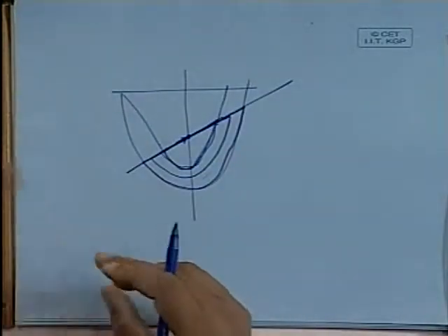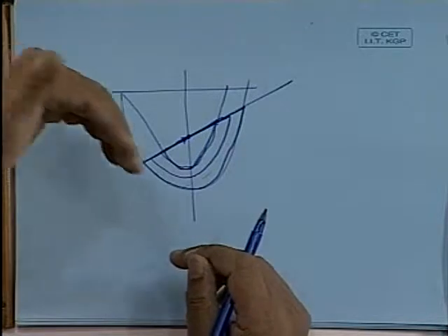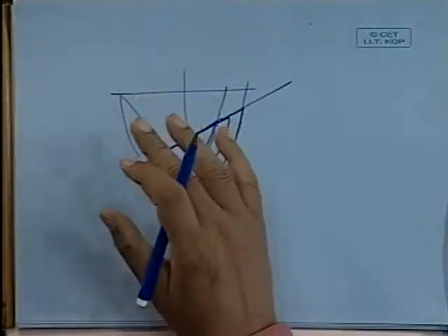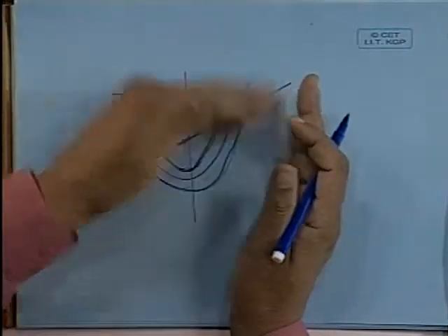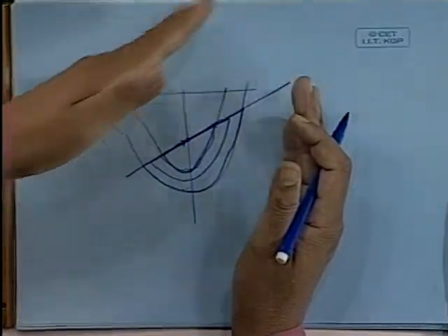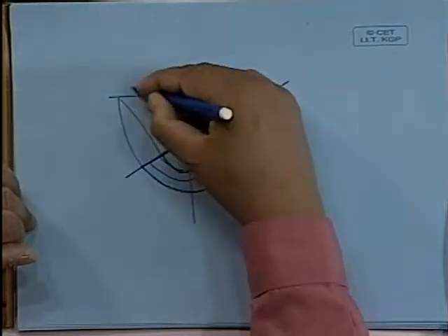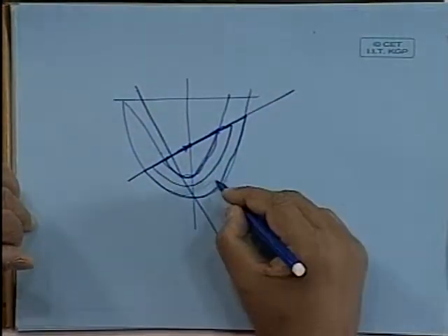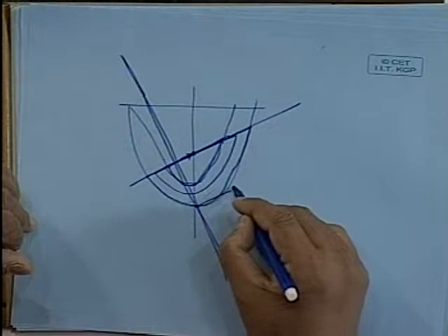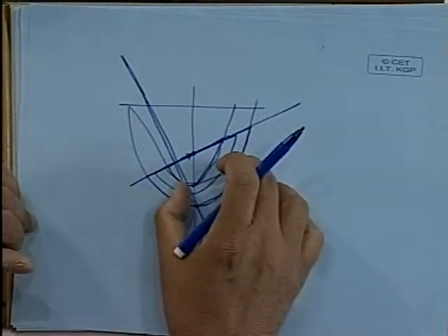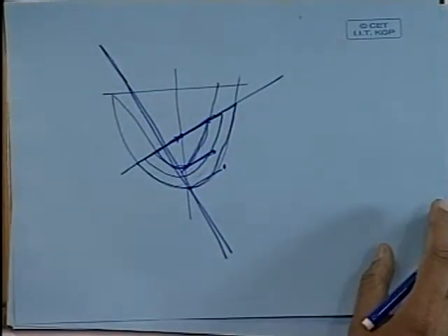Yeah, this integrator is actually a level higher because it does area as well as moment. That is why a planimeter is nothing but a simplified integrator where it does just area. Here it is area plus moment, as you set that for the moment you can set an axis. So this axis will be set because you want to find the moment about a line perpendicular to this. See, if this is the axis chosen through this K, then you will get directly the moment, and if you divide that moment, then you get the KN directly, or rather this transverse distance. From there you can get KN. This is the idea. The full idea is that.